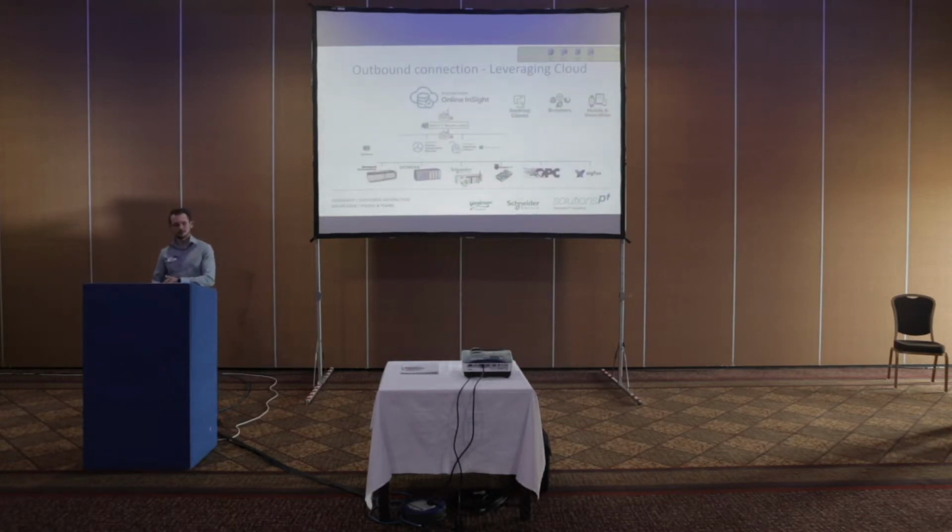And again, this is extending even further. So yes, the last example I showed you, getting data onto that online environment. But now we're starting to see these weird and wonderful devices coming online at the bottom layer, and perhaps are not part of your control system. So how do we get that data up there? We should still use the same security methodology to do that. We should still use that DMZ layer to get that outbound data push, and make sure we have the local store and forward of the data to ensure that if we lose any connections, then we can still access it at a later point in time.